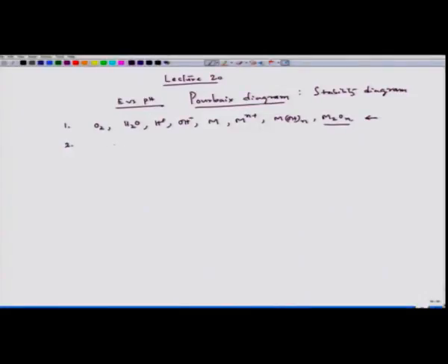So, let us categorize those reactions. One reaction, for example: in water we sometimes have dissolved carbon dioxide that can react with H2O and form H2CO3. As I have said, this reaction cannot be plotted in the Pourbaix diagram of a metal, but this is a weak acid, and it would lead to a certain pH of the system that can affect the corrosion stage.